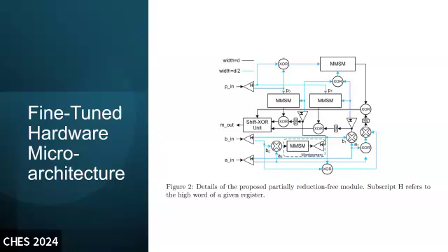Then this is just a small-size modular multiply, but in terms of the whole partial reduction scheme, you can look at the figure here. In the beginning part, we split them into 2 using the Karatsuba. Then through different stages there is one small Montgomery multiplication involved.